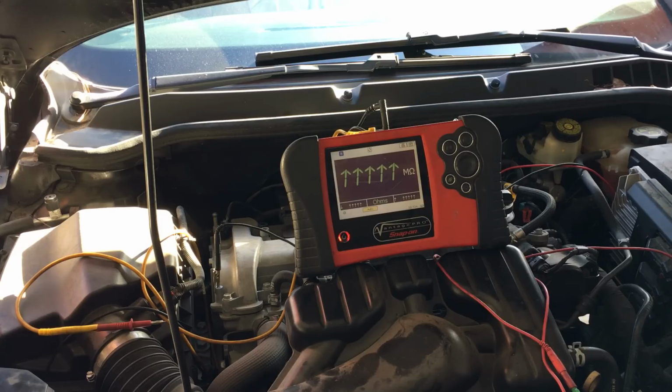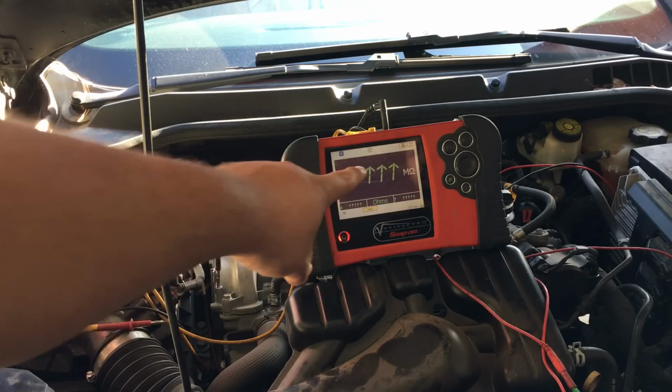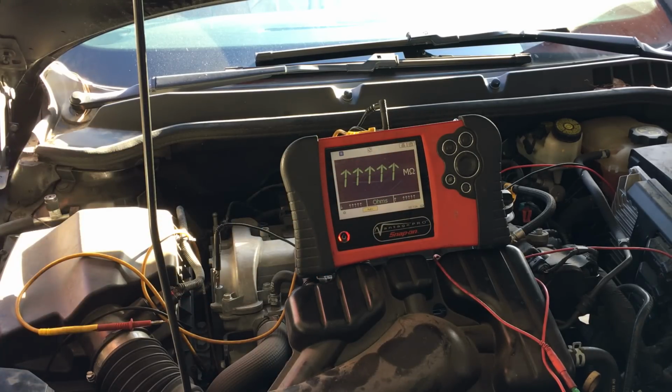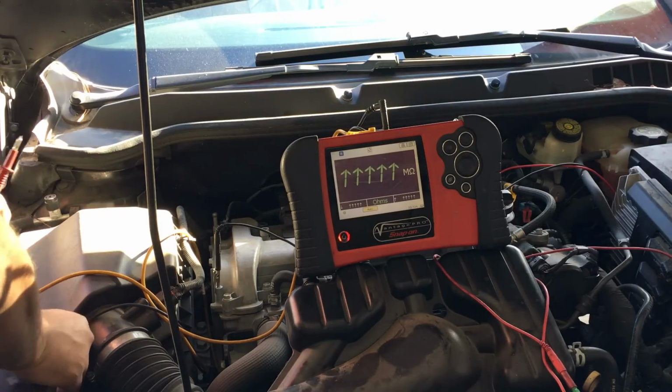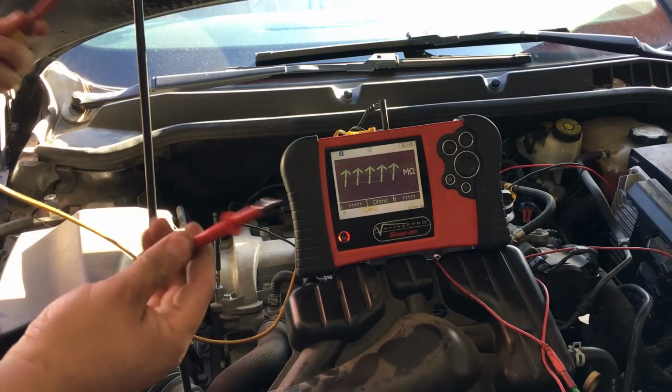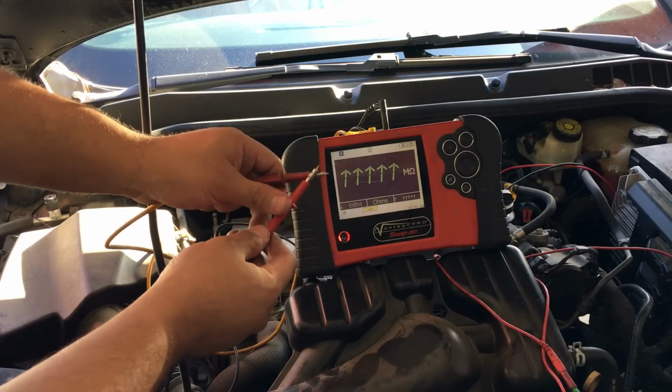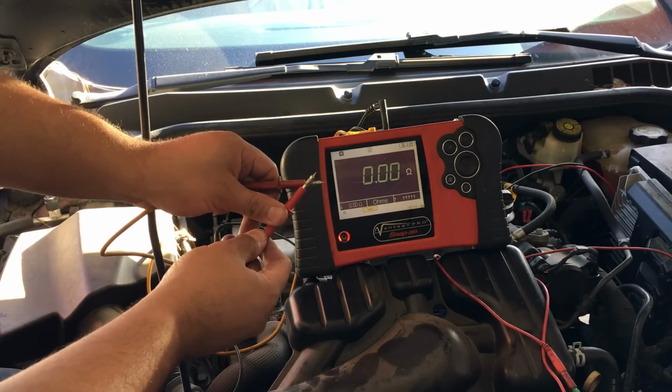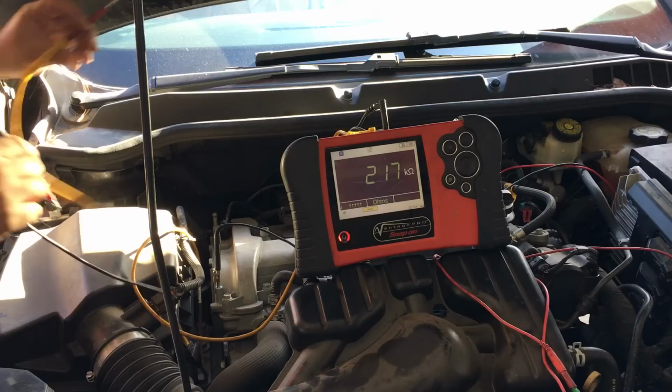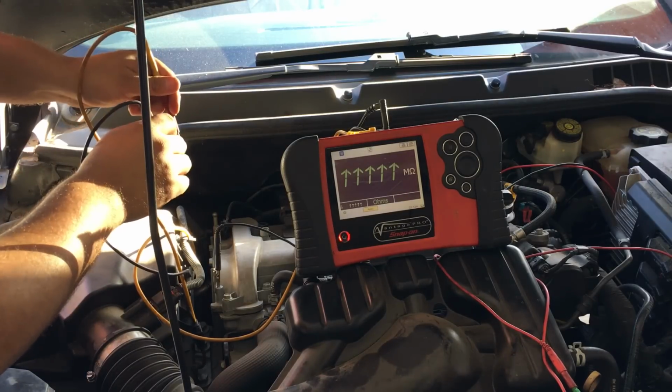All right guys, so moving back under the hood. You can see I've got my lab scope set up as an ohm meter, and I've already gone ahead and calibrated the leads. So I've got these two right here. You'll see that when I touch them together, my meter goes down to 0. Now I'm going to touch the two pins on the intake solenoid.